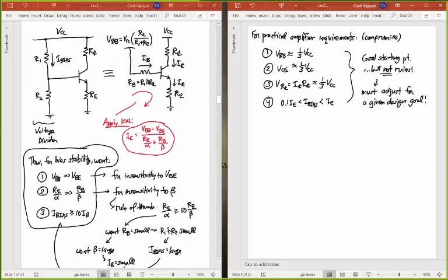Okay, so that's bipolar biasing. And again, the game here, just a reminder, is to get a certain collector current out of this. With bipolar biasing, it looked like I went through a lot, but it actually was made very easy because we could say our VBE was equal to 0.7 volts throughout this whole thing. I showed you examples last time how we did something like that.